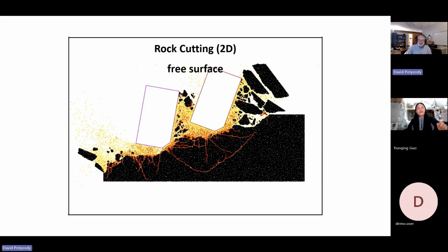So think about this. This rock cutter, most of the energy, most of the work that it's doing is basically forcing itself to flow over granular material. There's very little energy required to form these big chips. They happen really fast. And then most of the time you're grinding this across granular material. Now, what you have is granular material flowing along this surface.